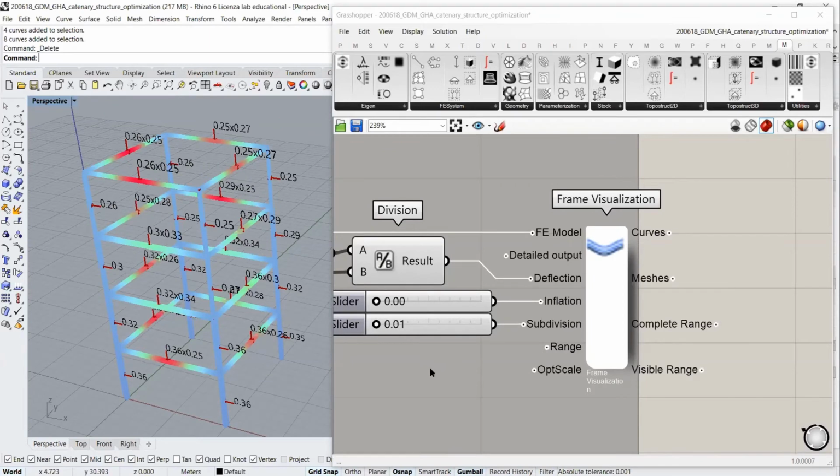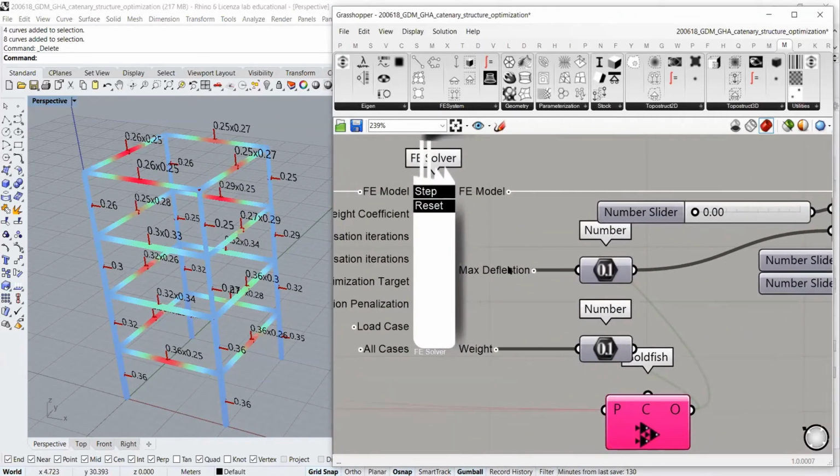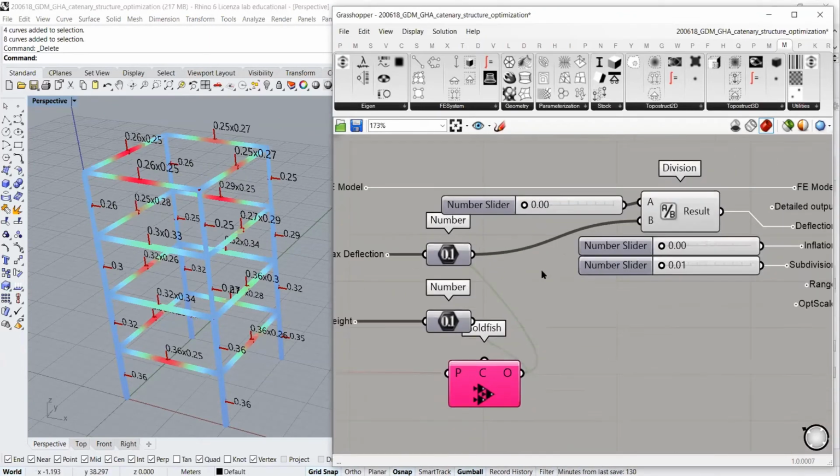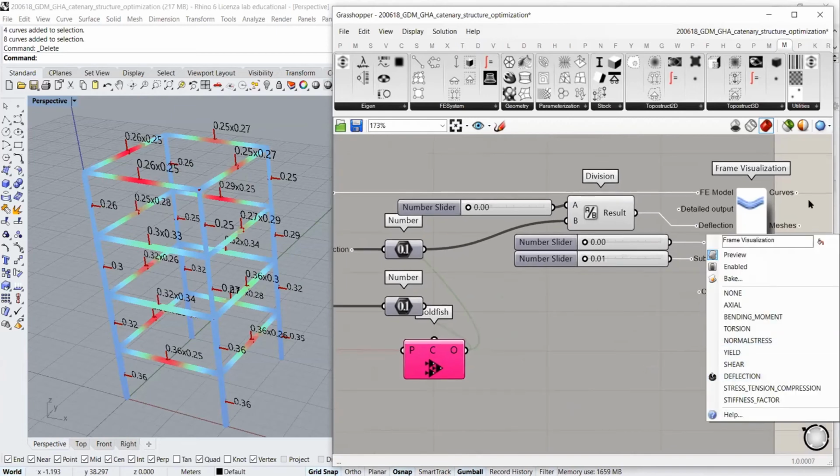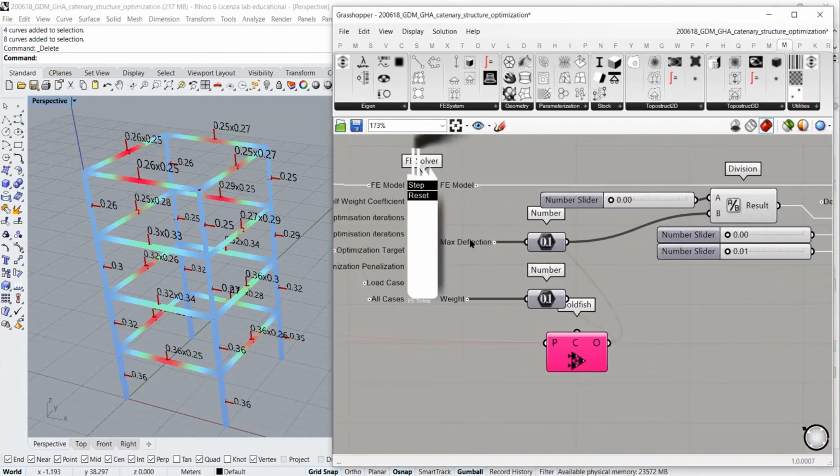But remember that we are showing the deflection, and the red corresponds to the maximum deflection. And the maximum deflection is 0.000291. So this is the red. So when you see red, it's not necessarily bad. If you are running an optimization, the red will always correspond to the maximum deflection. But if you have optimized the deflection, then it's going to be a very small value. So red doesn't mean bad in an absolute way. Okay.